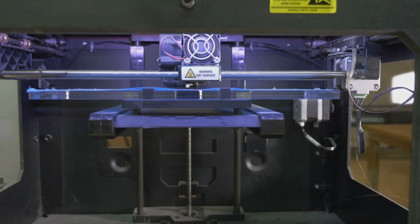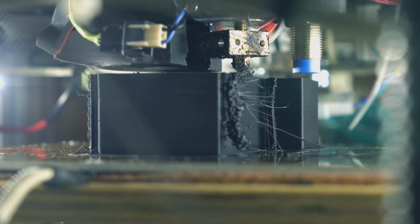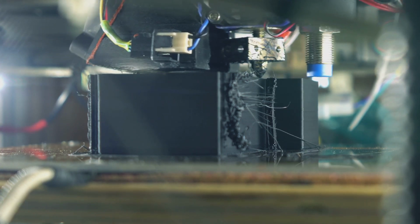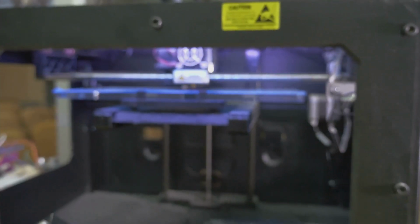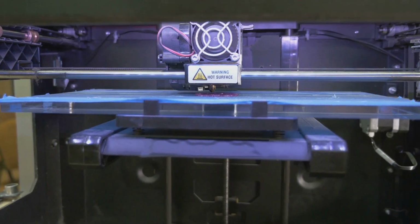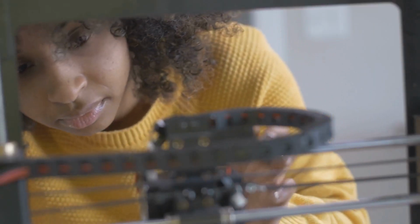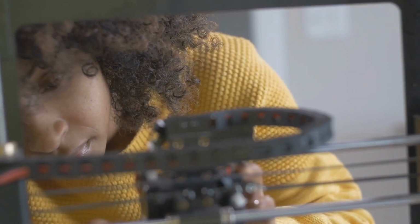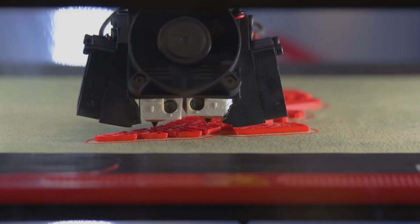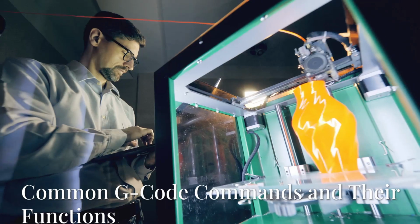But M-code does more than just manage heat. It can control the cooling fan, which helps to solidify the extruded plastic quickly and prevent drooping or stringing. Some M-code commands can even control advanced functionalities like switching tools on multi-extruder setups or engaging self-leveling routines. By mastering M-code, you gain granular control over your printing environment, allowing you to fine-tune settings for different filaments and achieve optimal printing results.